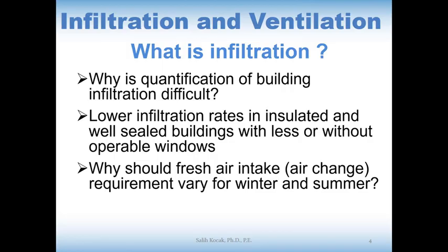The main thing that we covered just one class before this one is the conductance and resistivity of the wall and its members and parts, and also the conductance through the resistance values. So in winter time, the temperature difference between inside and outside is going to be high, and also there will be wind. That's why the winter air intake is 50% larger than the summer one.